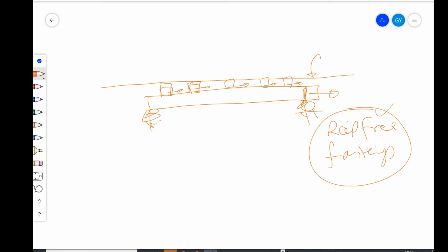So, the presence of rail-free fastening has created a situation where the interaction between the rail and bridge is not taking place. Or what we call is, rail and bridge are not coupled structurally, or they are decoupled by way of rail-free fastening. Same thing will happen if my deck is bending, right? If your deck bends and deck shortening happens on both sides, the sleepers will move, and there is no difference to the rail.